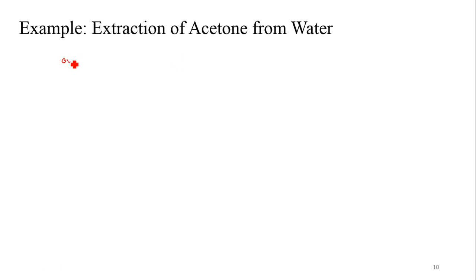So what do we have? We can think about an overall mass balance. This would say something like M_S, our solvent, which we were feeding, in this case, 1,000 kilograms, has to be equal to the masses of the extract and the raffinate. So M_E plus M_R.